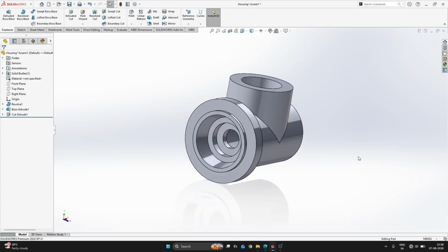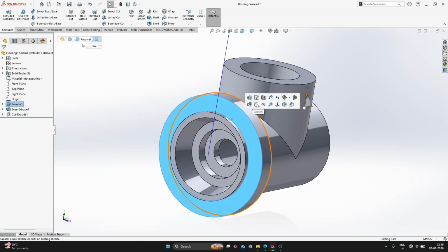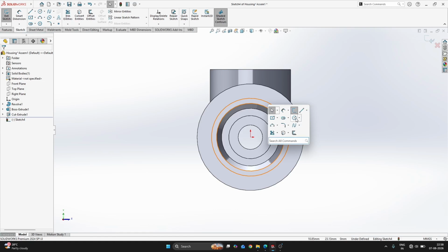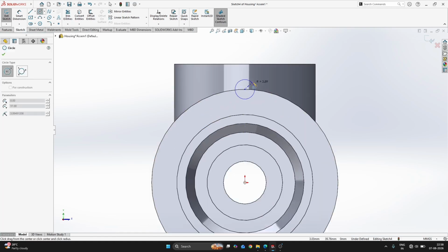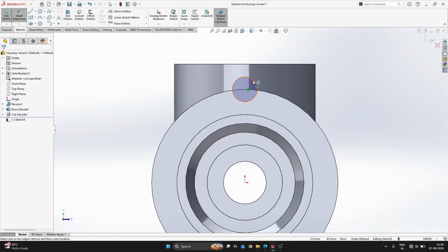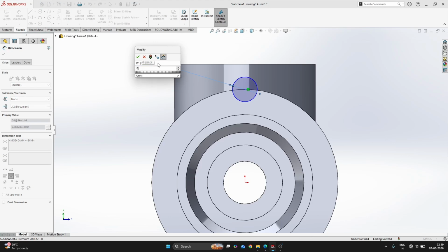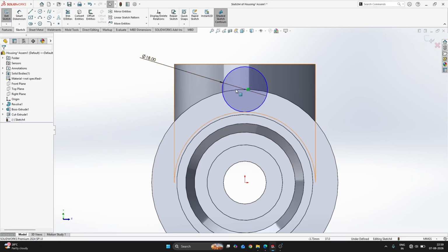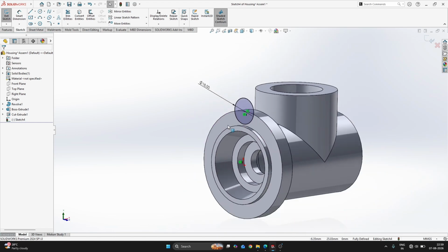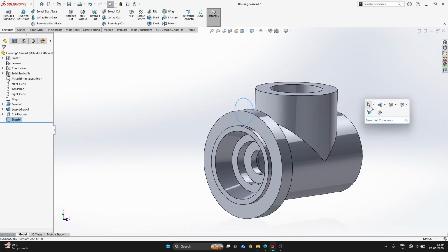Okay, so click on this plane, sketch, next circle. What is the radius? 9. That means 18 diameter there. And set this point vertical, make it vertical. Okay, this is fine. Now exit. You can make the cutouts, but I'm not doing that.